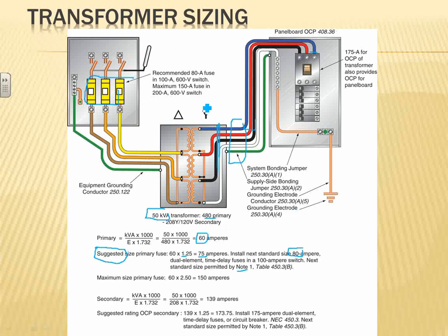On the maximum size, look at the maximum size that they use. Maximum size is 2.5, gives you 150. So there's a choice you have to make between 150 amp fuse and 80 amp fuse. If you use the 1.25, and I'll show you that with the coordination, you are right up to 95% of the time. If in doubt, you guys have SKM. If you're in doubt, and when you know what type of fuse or circuit breaker you're going to use, just run an SKM analysis, and I'll show you in a second.